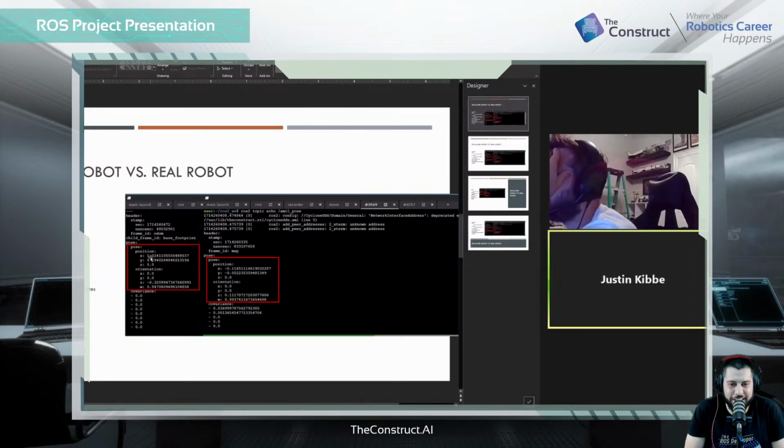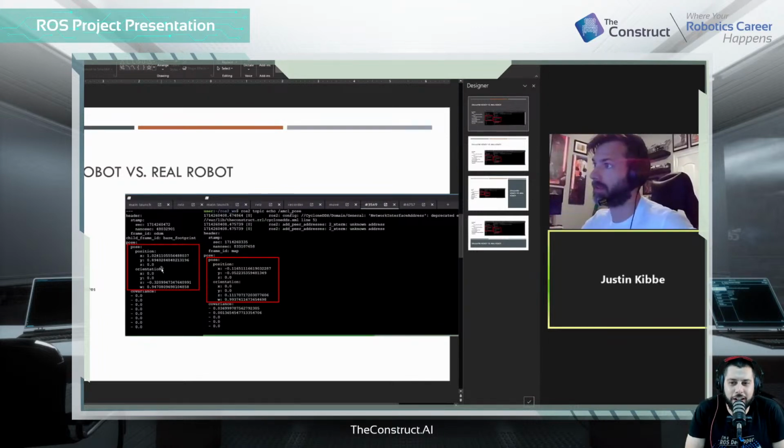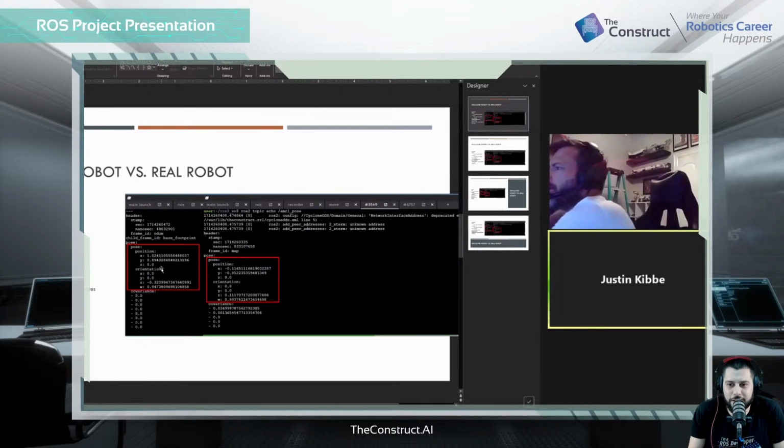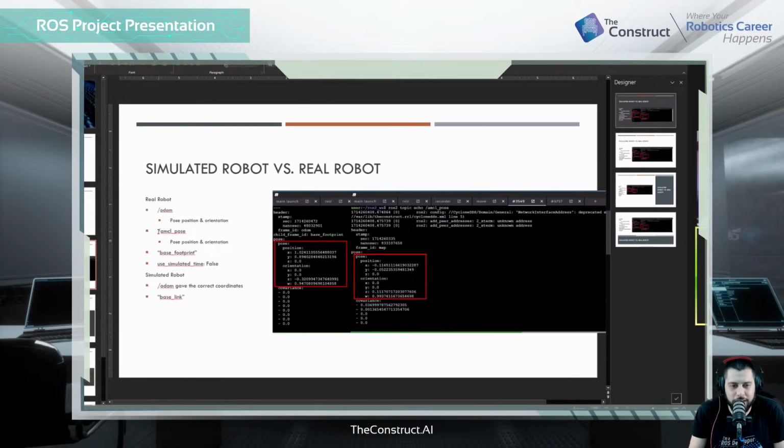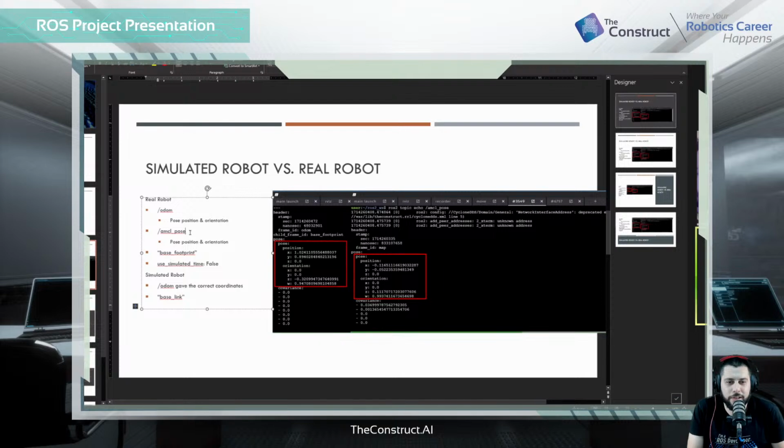But here, on the left, circled, is the position shown by the odometer. On the right is the position by the AMCL pose, and this seemed more legitimate to me because I know that we had been doing the navigation, studying the AMCL and all of that. So I changed where I was gathering my data from to this AMCL pose. And then after that, everything went perfectly.